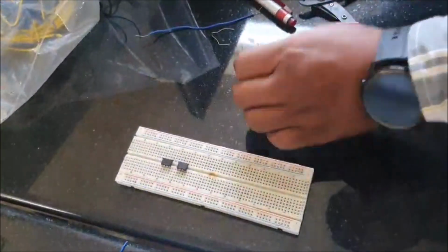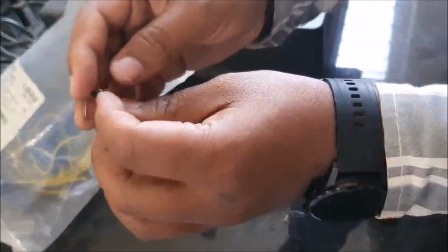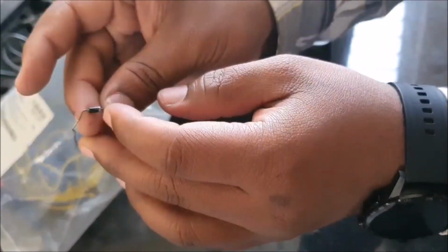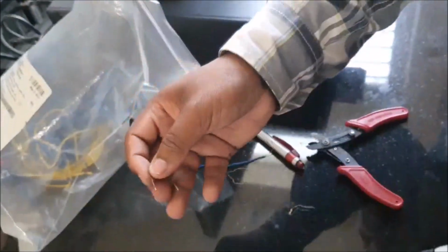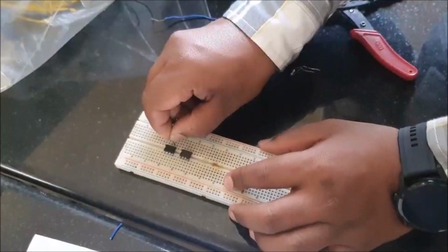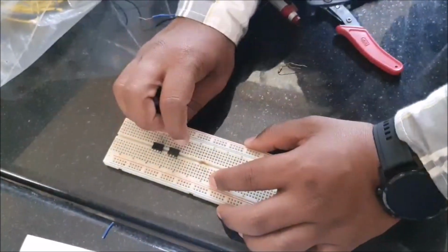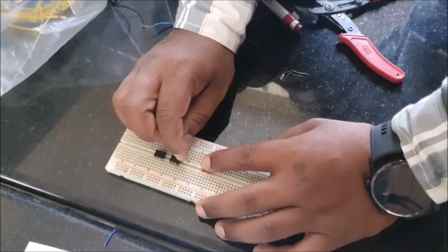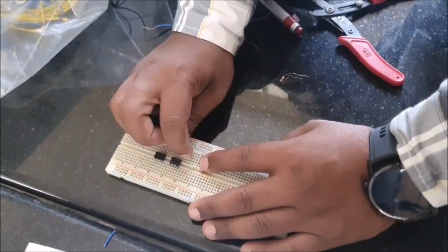So after connecting this, I will take two diodes. See here, a diode has a positive terminal and a negative terminal. The positive terminal of the first diode should be connected to the sixth pin of the first IC, and the negative end should be connected to the junction. So here I will select one series on column 3, and I will make that a junction.